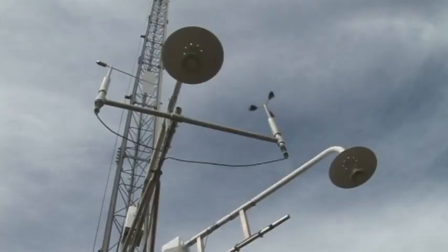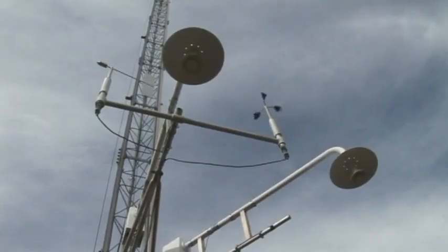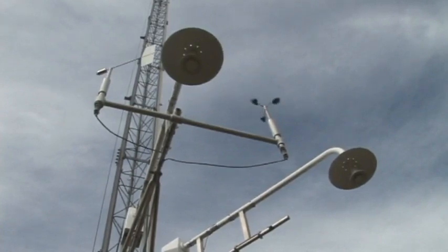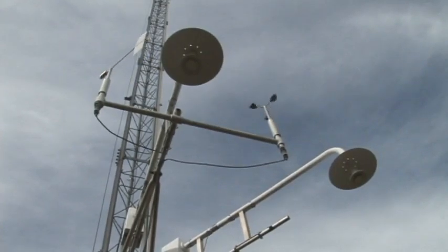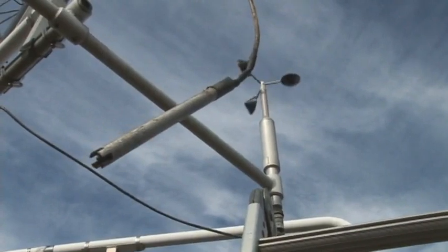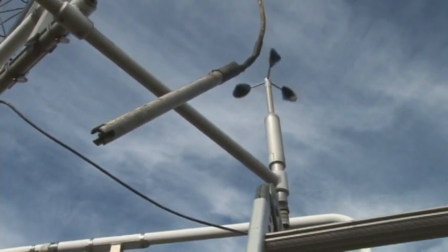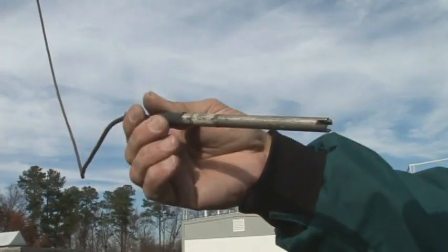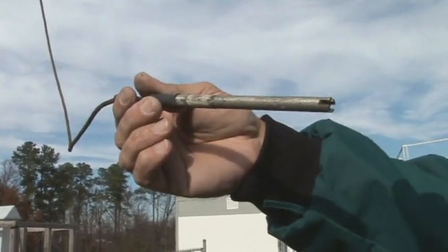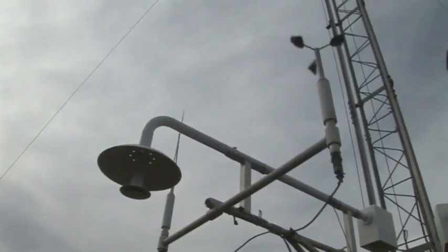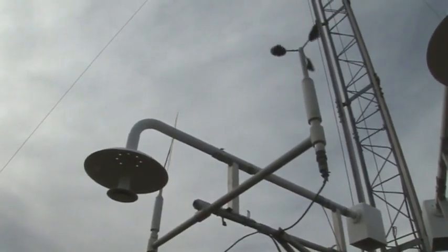Towers are not always needed for temperature and relative humidity sensors. Sometimes they can be mounted on the top of a shelter railing. Temperature probes or sensors must not be exposed to sunlight. A temperature probe can act as a thermal mass and absorb sunlight and give false readings. Temperature probes must always be housed in a protective covering.